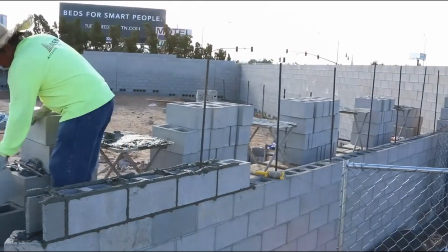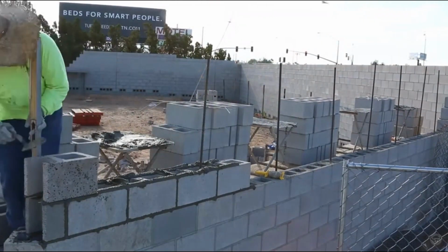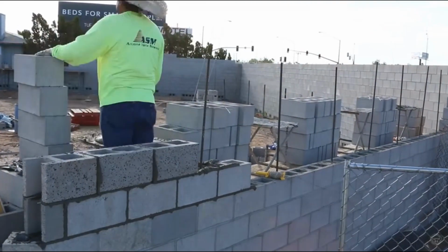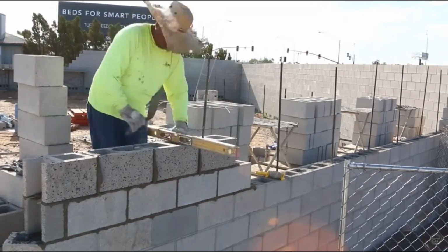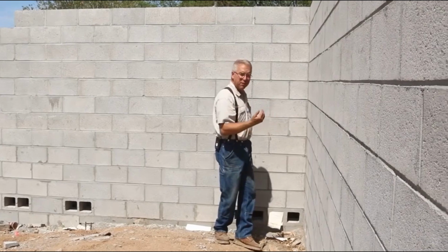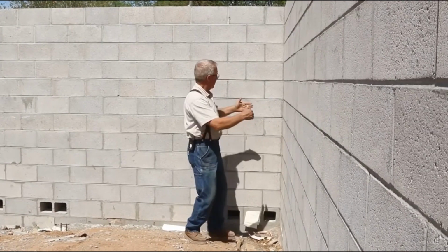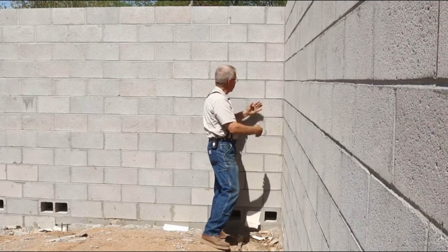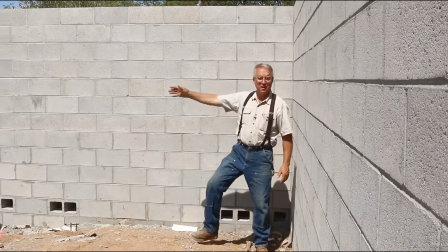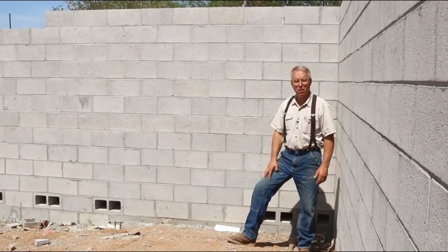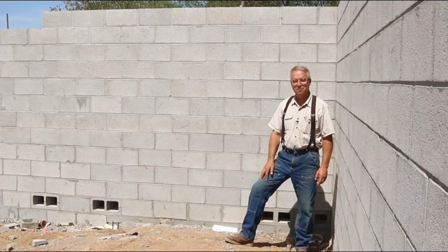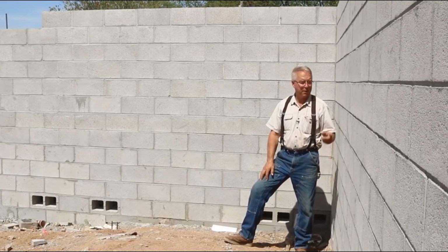So think of the mortar as glue. It holds the blocks where they need to be for a period of time until the next very important step happens, and that is the grout is put into this wall. So in this corner, the strength of these 2 walls to resist overturning is coming from the corner. I mean, you can't turn this wall over because this wall's tied into it and vice versa. But by the time you get down to the middle of a 550-foot wall, you are a long ways from the corner, and the strength needs to come from somewhere else. In this case, the strength is not coming from the mortar.